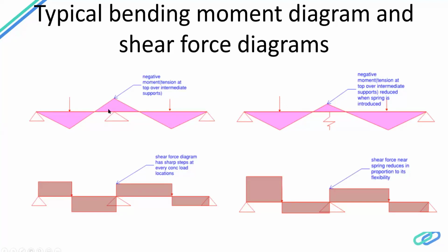And then if you see here, you see a maxima in the negative moment, and then once you go over here, you again see a local maxima here as well. But in terms of magnitude of these moments, like this moment versus this moment versus this moment, all of this is actually a function of the stiffness of these members and the spans of these members.